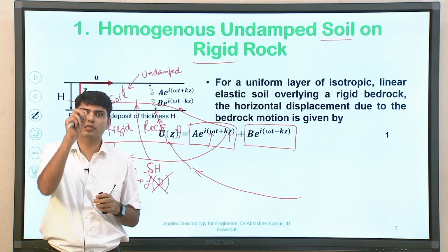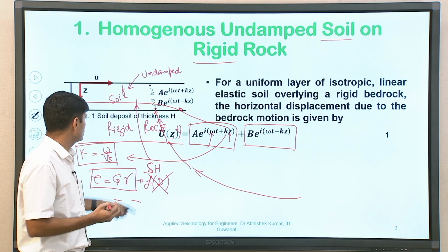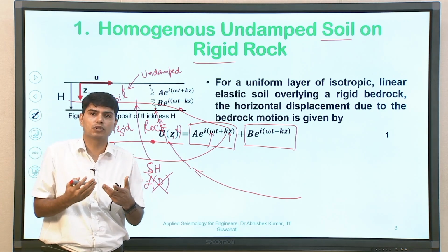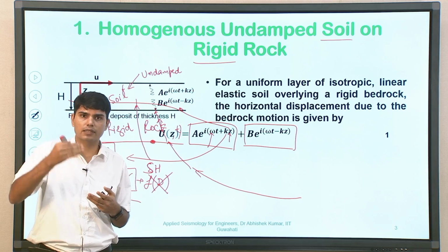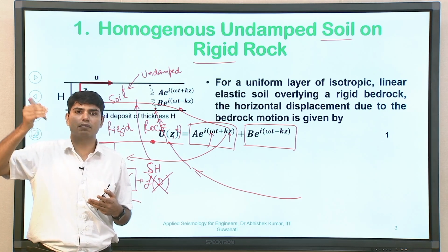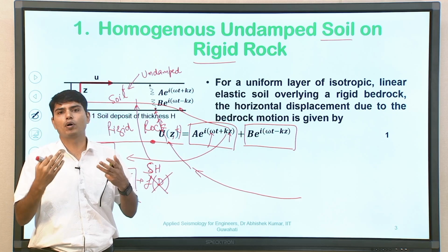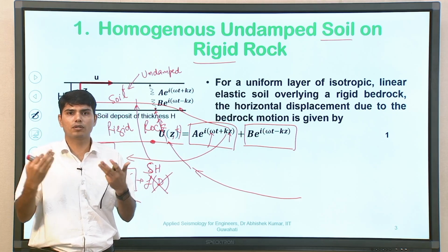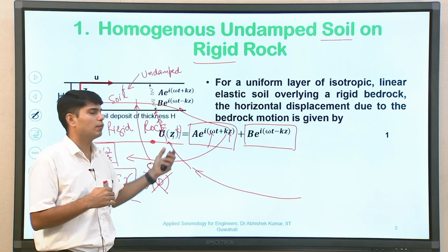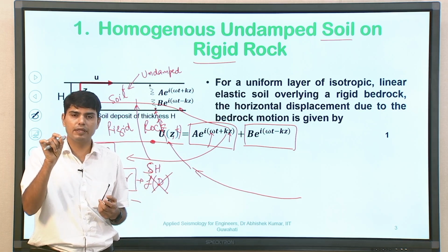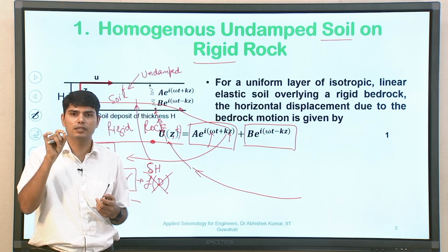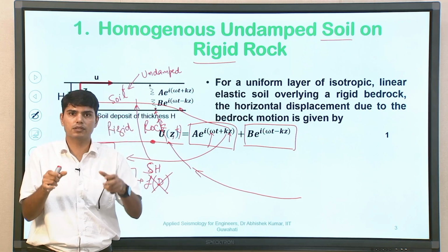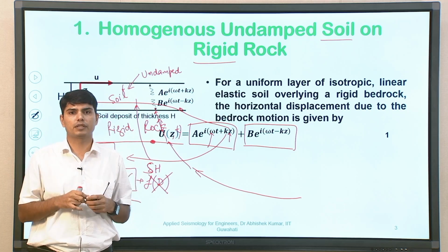Incident motion characteristics means, at your observation point, which may be this particular bedrock condition, what the ground motion characteristics are, how much change there is in the acceleration value at a unit time interval. It can be 0.05 seconds, depending upon the rate at which the sensor is detecting the change in displacement, velocity or acceleration values, that is going to give me the complete record, which is basically the ground motion of interest.